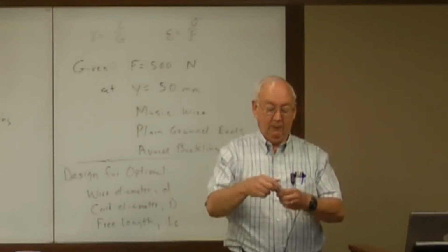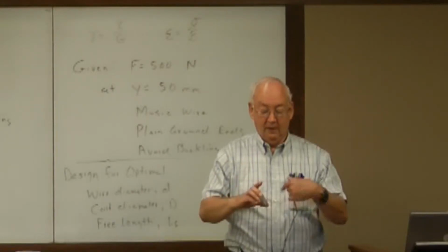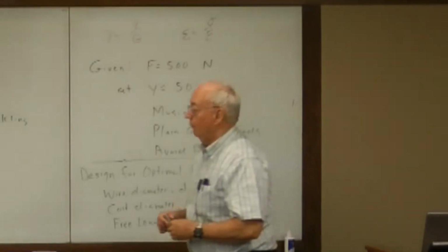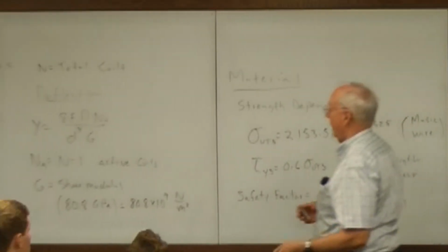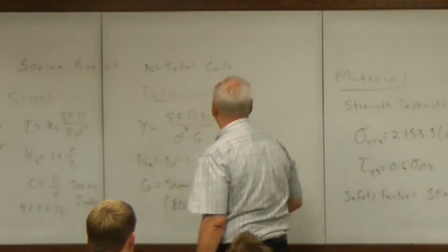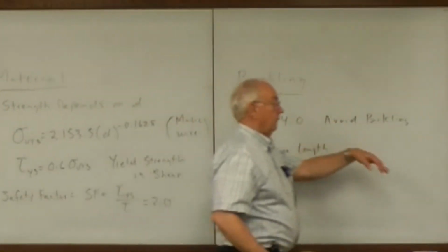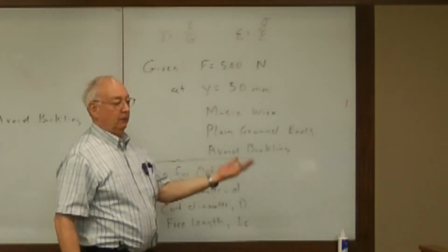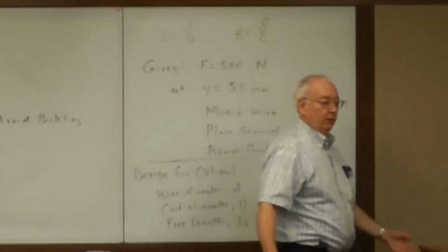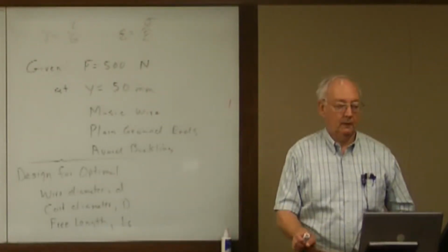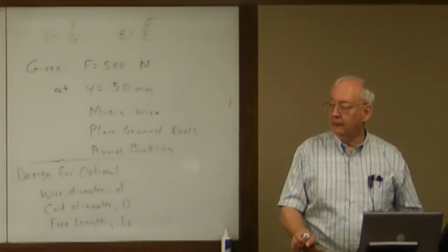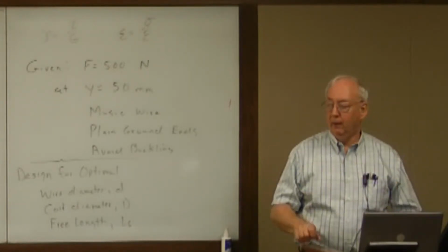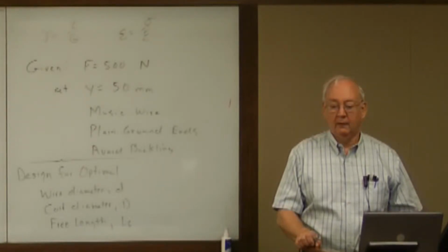So when I get an odd number of coils coming out of my design, I just make it an even number. And then changing that number of coils to an even number to make a reasonable thing throws one of these things off a little bit. So I usually say, well, I don't hit the deflection quite right at 50, it's 49.5 or 50.5, which is okay, a couple % off. So that's where I let that couple % come off, to try to make designs that are sort of even numbers. Not necessary.